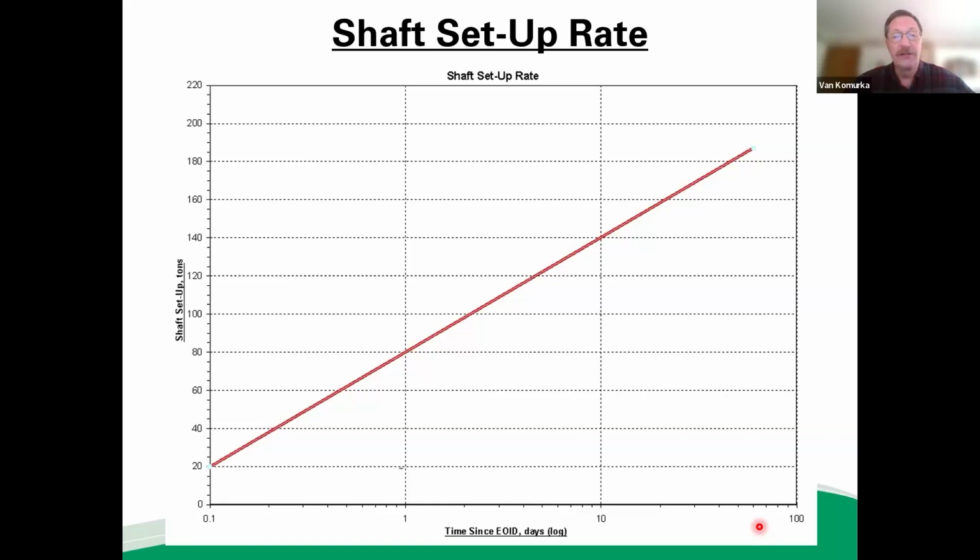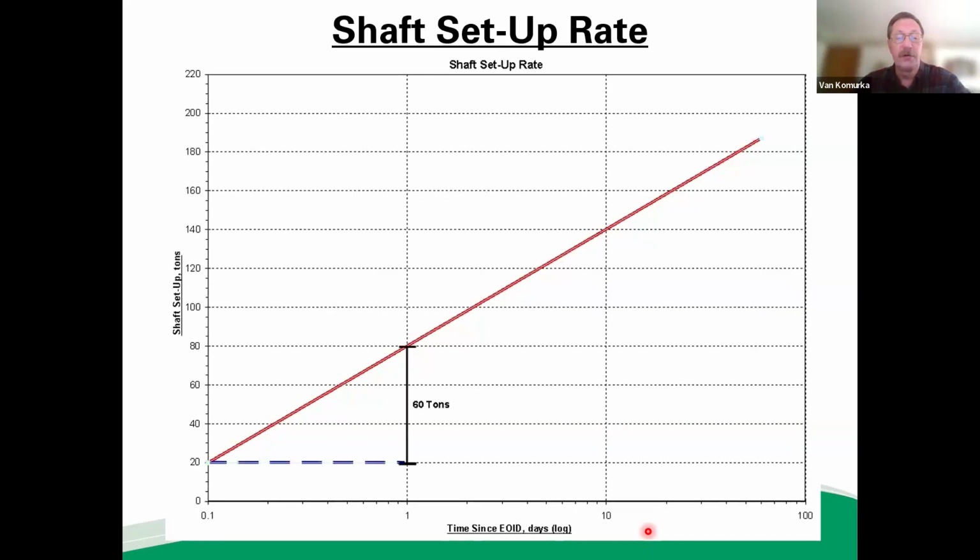It's just like soil consolidation because excess pore pressures are dissipating. So once we realize this, there's several things that we can learn and instill in ourselves and our clients as we talk about test programs and how setup behaves in the natural world due to this log relationship, and how we can then kind of structure our test programs.